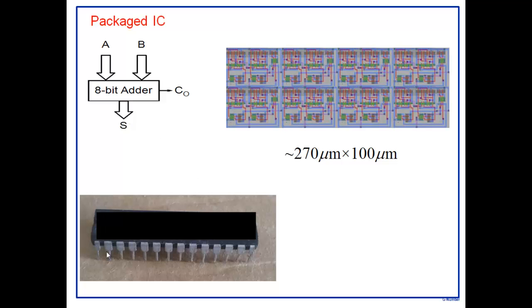So what I've done is I've taken, I think, a 28-pin IC, a 28-pin package, and one can take the whole adder that we have designed, place it in this particular IC here, and connect the appropriate pins. You connect the appropriate terminals A and B to various pins, and you need VDD and ground and all of that also.